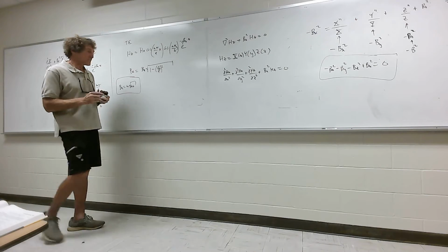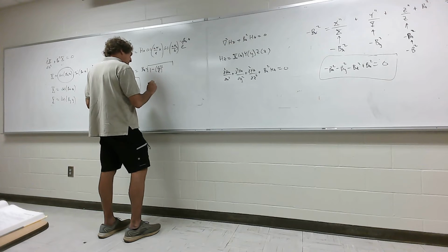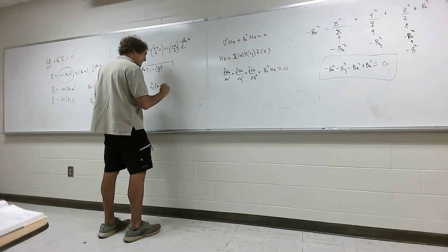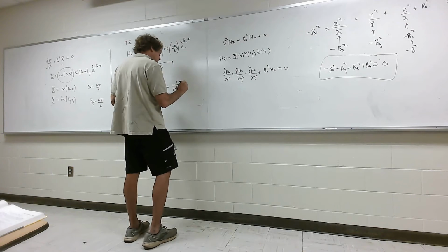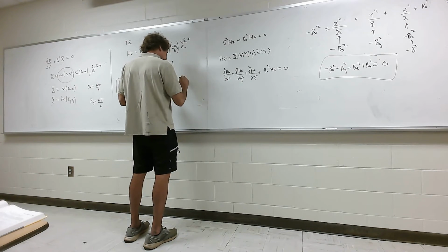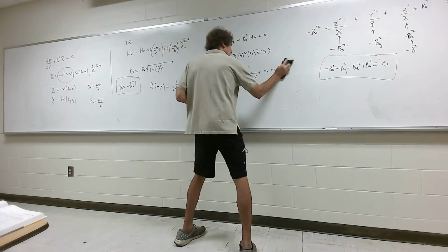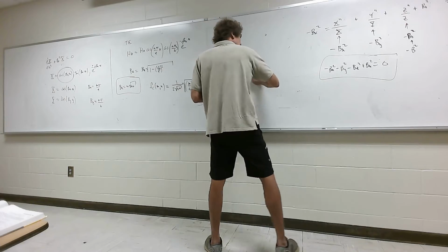And remember one other thing, fc in general, now I'm going to make some other comments in a second. fc is a function of m and n, the mode numbers, and that's equal to 1 over 2 times the square root of mu epsilon, times the square root of (m over a) squared plus (n over b) squared. Write that down. It becomes a little more useful, I'm about to tell you.